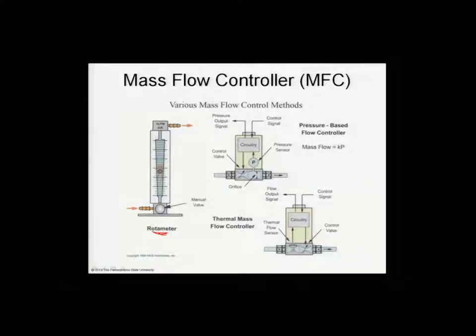Here's another type that uses a pressure sensor. Depending on the speed of the gas, the pressure sensor gets different readings, and then with the pressure sensor calibrated on measuring pressure, the circuitry can then convert that pressure into speed of the gas. So this type uses pressure, and the calibration, of course, involves knowing how the mass flow is proportional to the pressure picked up by the sensor. So that's developed by the tool vendor, the tool producer.